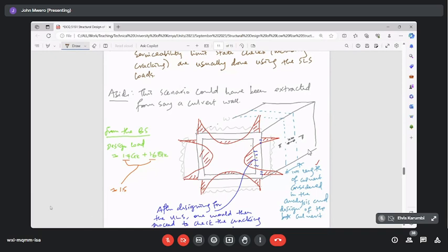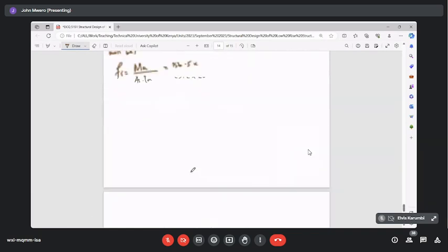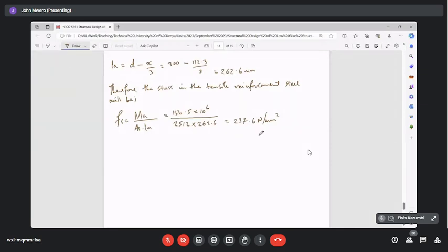This is the number. This is the stress. This is the stress that currently, under that applied moment, with the depth of this section, with the thickness of this section, it actually feels 237.6 newtons per millimeter squared of stress.